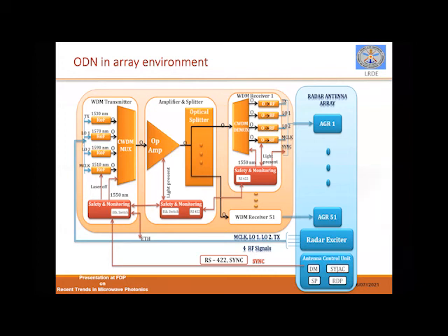When your number of signals are more, you can use DWDM. It differs with the spacing between the channels. In the case of CWDM, commonly it is maintained around 20 nanometer, and in the case of dense WDM, it differs with 0.2, 0.4, 0.8 nanometer.